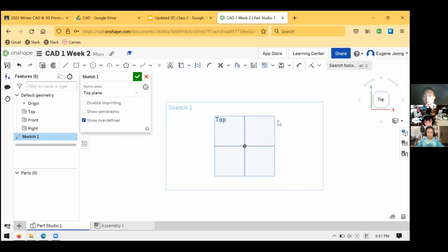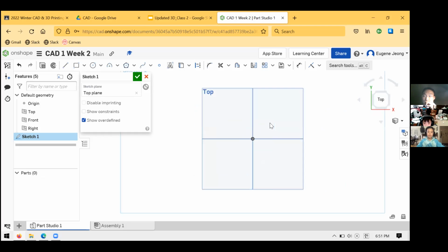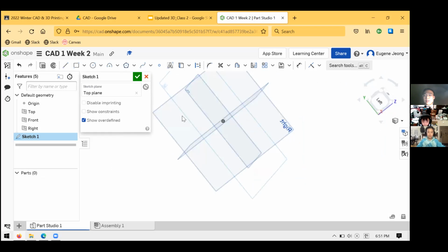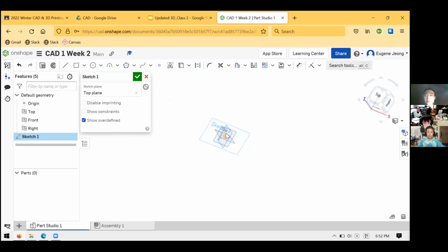Yes, do you have another question? Yeah, when I go in and I just touch top, how do you get out of it? To get out, remember your general rotation control method is going to be with your mouse. If you hold right click and drag your mouse around, that rotates your view, right? You can also click and drag to zoom in and zoom out. But right click is rotating. And if that doesn't work, you can always use your keyboard arrows or use the arrows on the navigation cube.